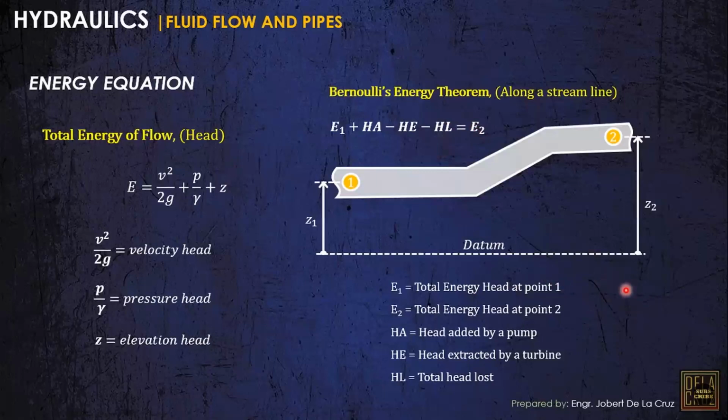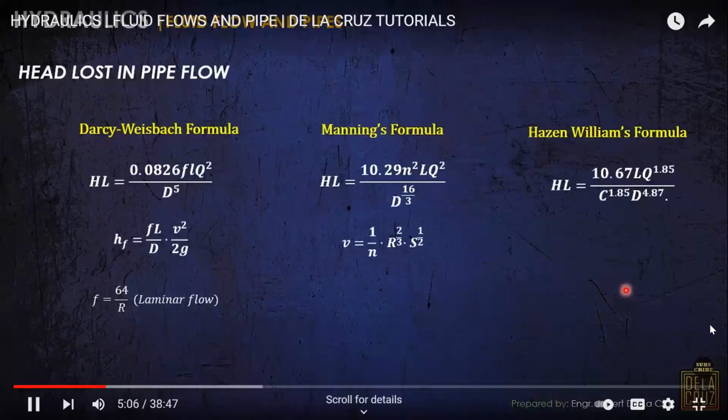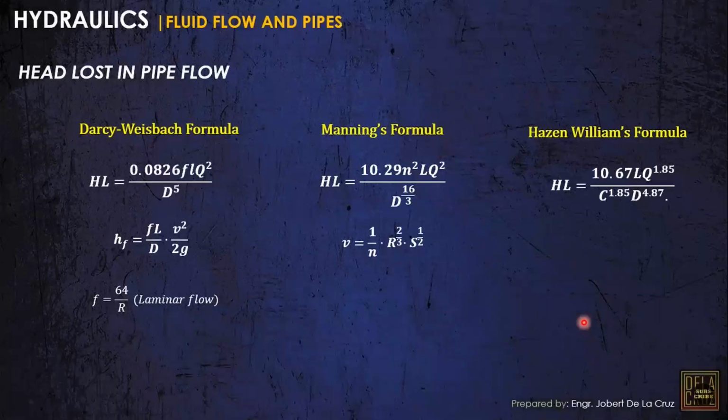Alright, so we have also to know this formula, no? Because sometimes in the Bernoullis equation problem will be involving head loss, and if we need to calculate head loss given yung these mga parameters nila, then ito yung mga formulas natin for Darcy-Weisbach, Mannings, and Hazen-Williams.